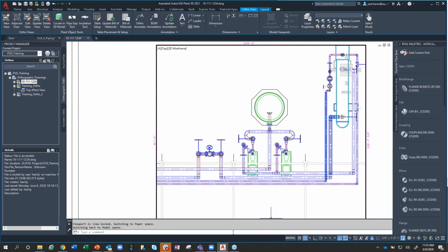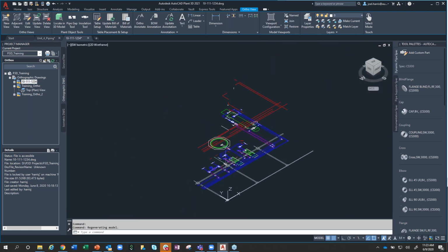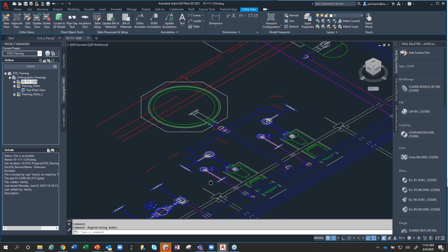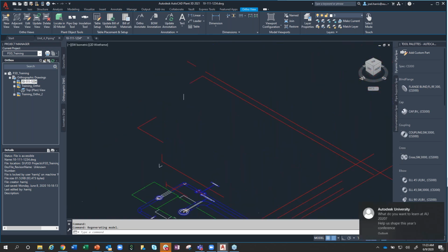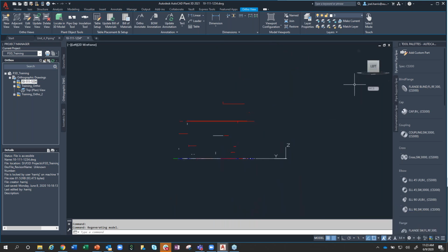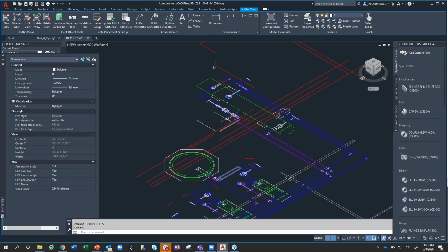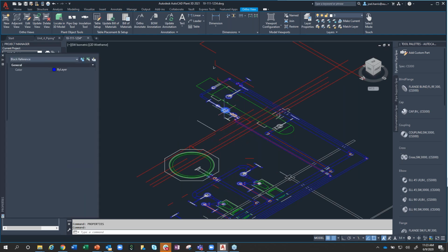I'll set tile mode, and we'll go into model space and you can see this. There's all the blocks that are in the ortho view, and they're located at Z elevations pretty much of where they would be in the 3D model, if I look at it from the side there. But each one of these, if I go to the properties of it, I always like to get into the hood, so hope you don't mind.